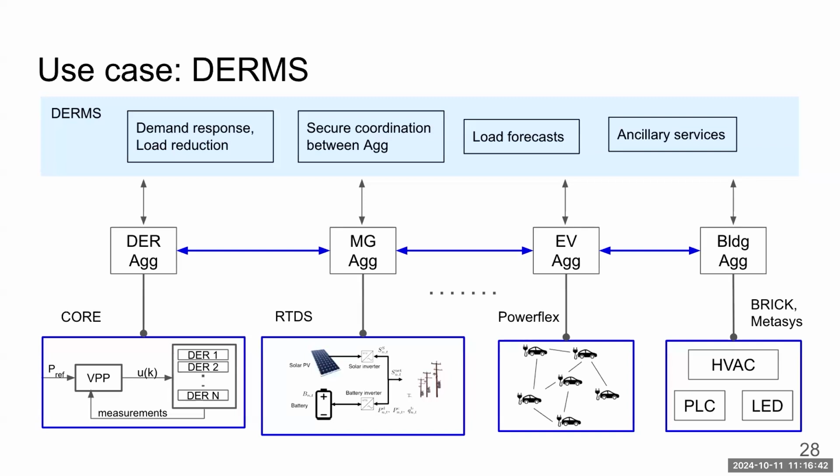This frequency is out of balance sometimes, so it should be 60 hertz, but actually it never is. And so if you actually go plug into the power outlet and you measure frequency, you'll be surprised. So it's generally safe, I mean, it's not bad, but any frequency excursion is undesirable, so the operator always tries to keep it very close to 60 hertz. Thank you. Yeah, sure.